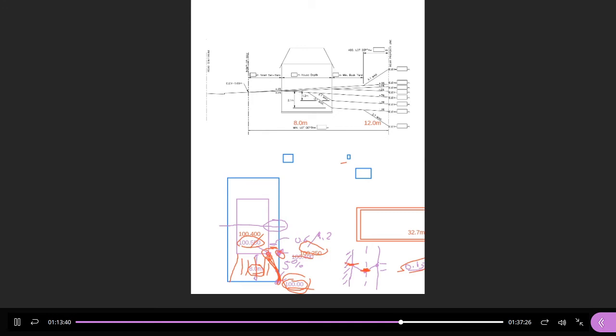Full usable backyard. Now again, if the backyard is much lower than the front yard, then we can start introducing that 3-to-1 slope, but down instead of up. So what would the usable backyard elevation point be here? What would the elevation here be? That last red dot I drew.